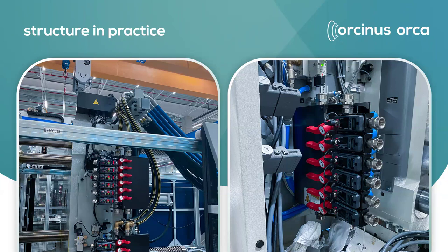Here you see that there are two different pairs of hoses coming to different manifolds. This could mean that the customer wants to have different temperatures at the mold, which is very common. And so from different TCUs, you can manifold different temperatures. So every manifold gets its own hoses.